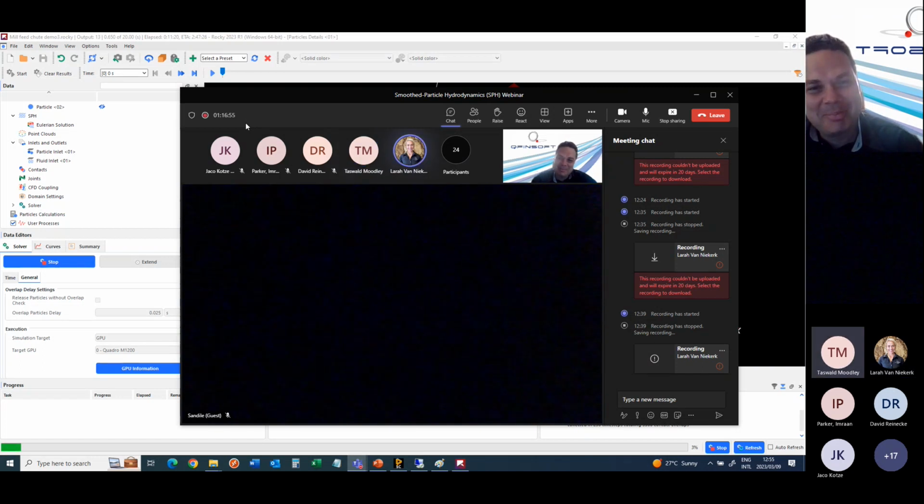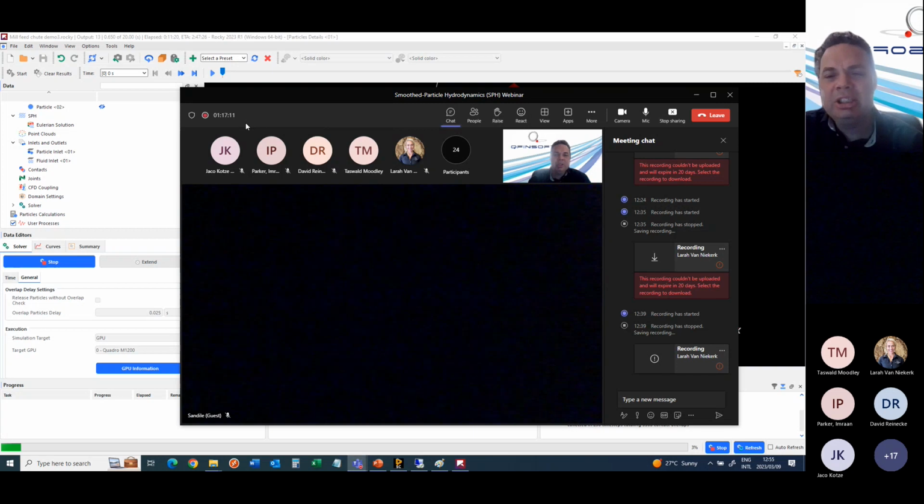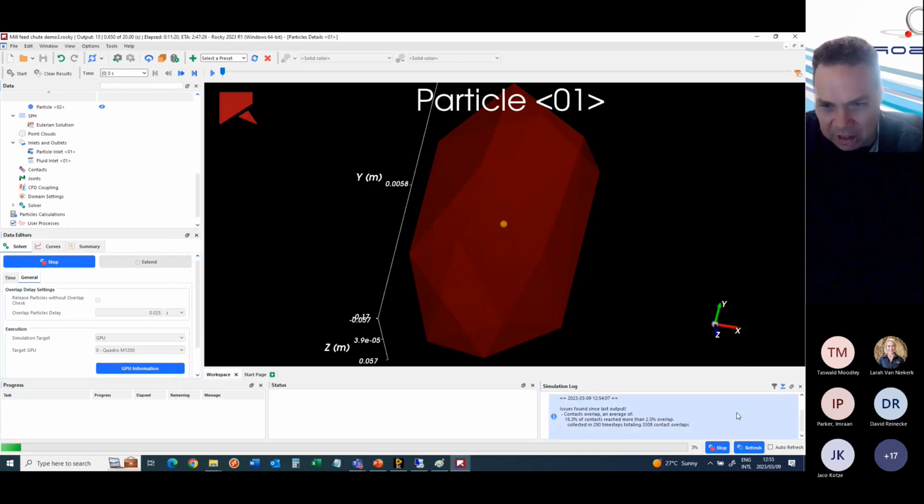Yes. What I notice is when I'm running the simulation, on the simulation log, it says that the SPH elements are clipped at the maximum allowable density value. Is that a physical limitation? So let's say if you want slurry that's above that, you might as well just put that value in. It's a limit. It's limiting it so the particles don't get too heavy. So it is based on the density you specified, as far as I know.